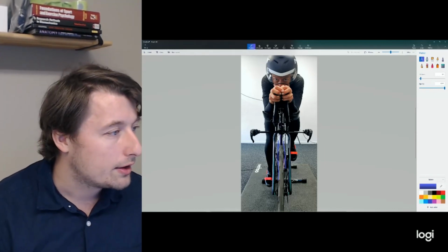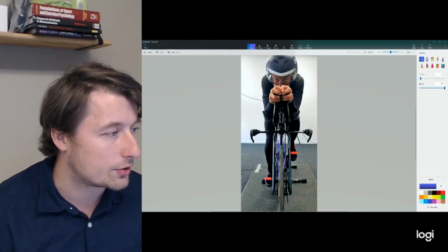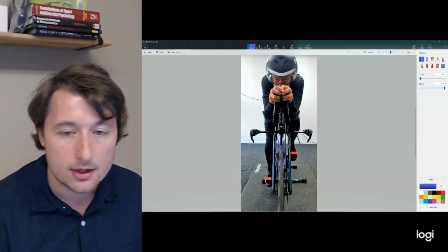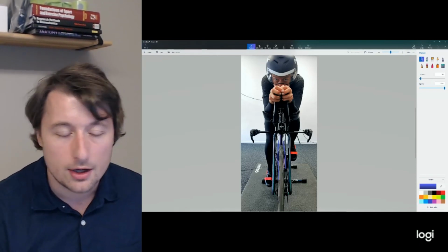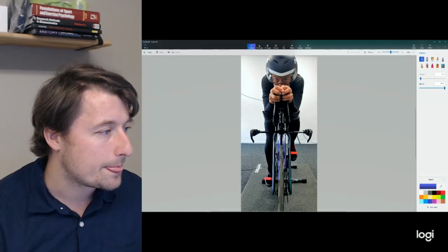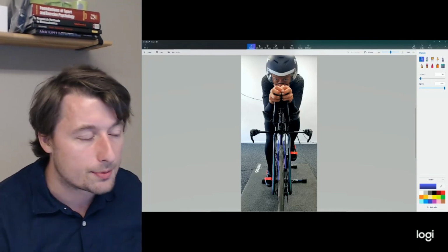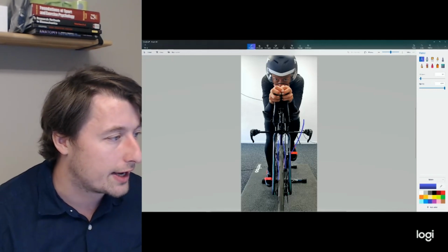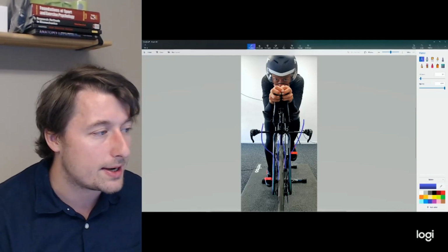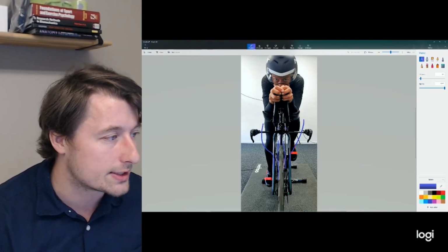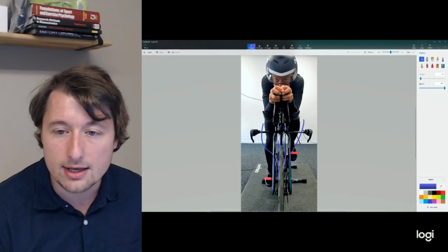As well, with the spaces up through here, we can see how that's going to direct the airflow between the legs. So then we're not as concerned about the legs creating turbulent flow, because we can direct the air around that. We can do similar things with the angle of a fork, for example, where it's going to divert the airflow around the legs in this direction. And with the spacer arrangements, we point things inwards to control where the air goes, because we need the air to flow somewhere.